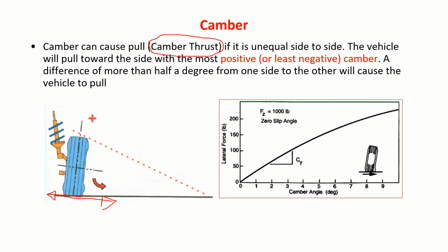When the wheel starts rotating, it will be pulling inside, and for that there will be a reaction outside, opposite to this. This reaction is what you call camber thrust. So to compensate, a camber thrust will be active.